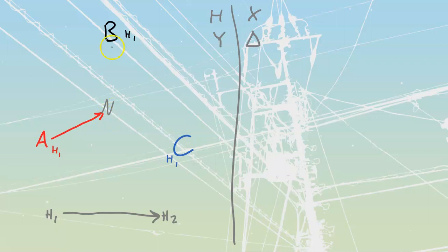Then I'm going to do my phase B the exact same way. I'm going to take my H1, I'm going to take my H2 to the center, and then I'm going to take my phase C, and I'm going to take my H1 and take it into my H2 in the center. At this point, I can label all the rest of these over here. So we're just going to make this one an H2, this one an H2, and this one an H2, like that.